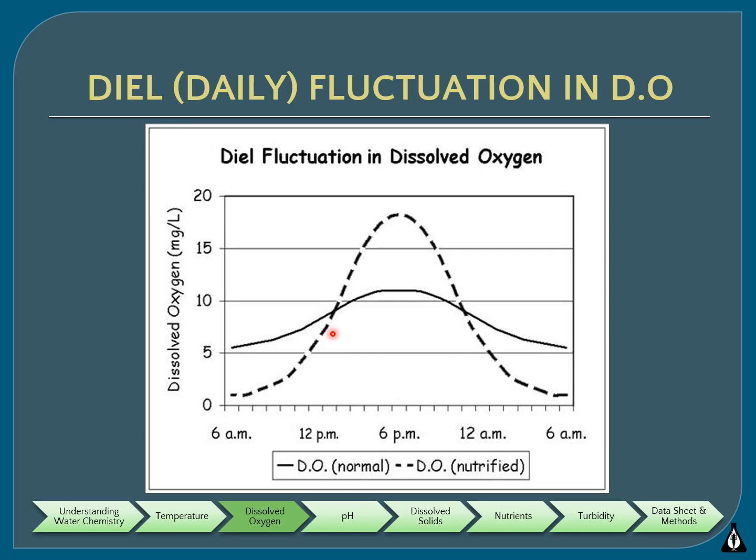However, if these processes occur to extreme levels, subsequent extreme fluctuations in dissolved oxygen, represented by this dashed line on the graph, can occur. Many factors could contribute to this, including removal of the trees from the riparian zone that would normally provide shade for the water and help control erosion. Also, if streams receive excess nutrients, like nitrogen and phosphorus from fertilizers running off the watershed, it may result in excessive production of algae. Excessive production of algae is often called a bloom and can cause extreme diel fluctuations in dissolved oxygen.